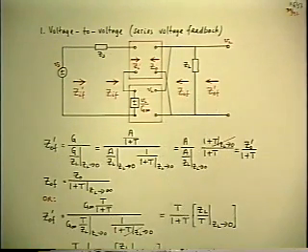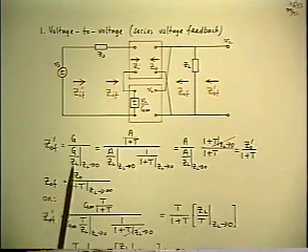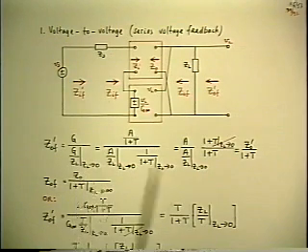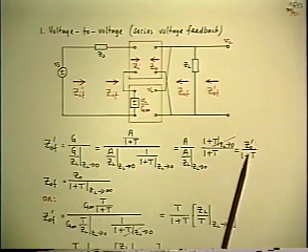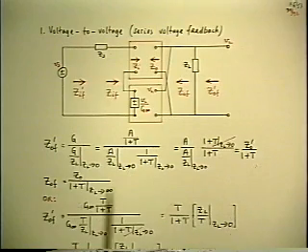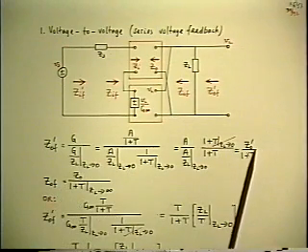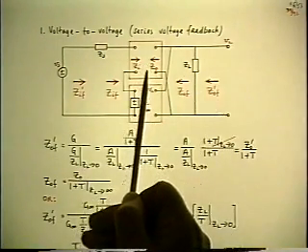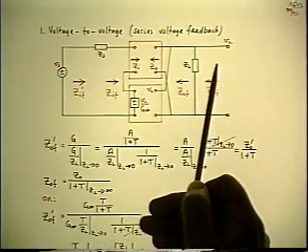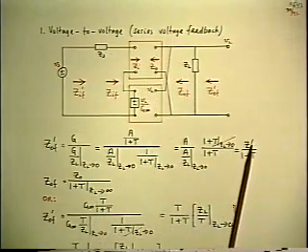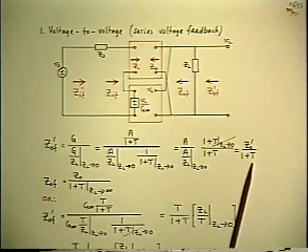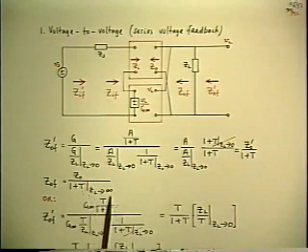without the prime. Well, you just take the other limit in the result you have already, same as we've been doing all along. So we take the result we have already, and it has two factors. So you take the other limit factor by factor, that is, you let ZL go to infinity. So that converts ZO prime to ZO. The original outside output impedance is converted to the original inside output impedance by letting ZL go to infinity. And in the denominator, you write T with ZL infinite.